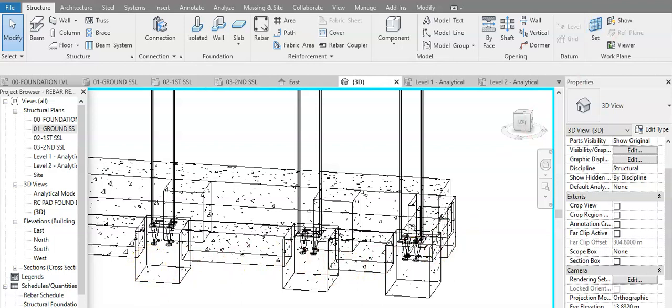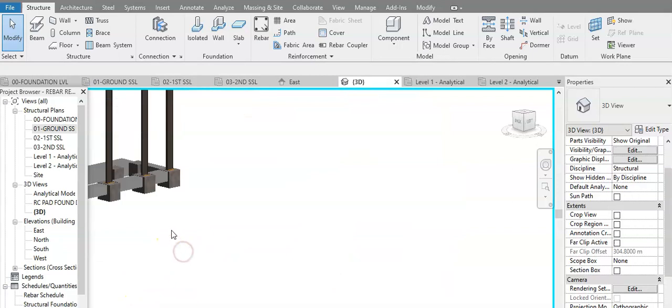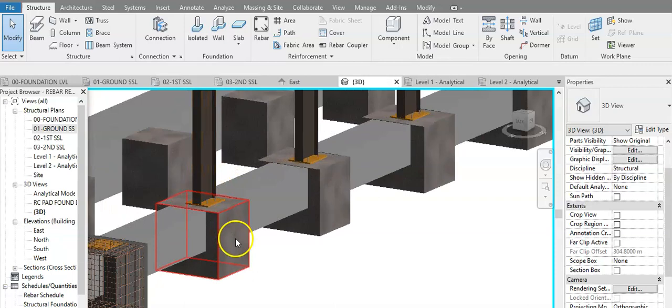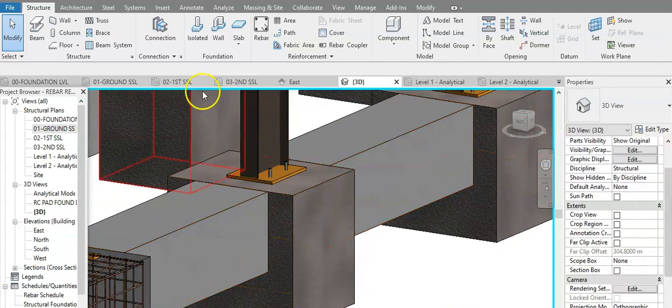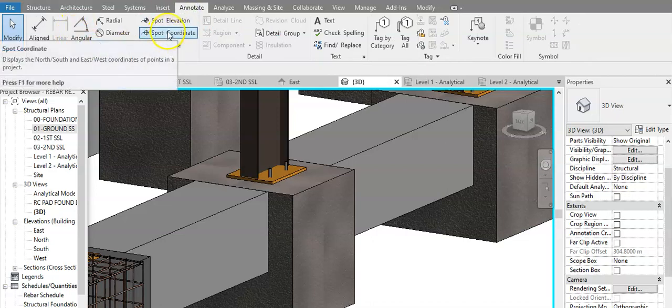Having been assembled and set out, the holding down bolts can be checked by the engineer on site to make sure they are all in the exact position, and a survey can be arranged to ensure that these are set out in the exact position, which we call the pre-concrete checklist.